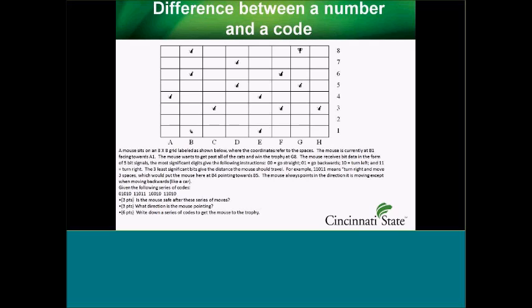It's a 5-bit string with the following instructions. The two most significant bits: 0, 0, the guy goes straight; 0, 1, he goes backwards; 1, 0 turns left; and 1, 1 turns right. The three least significant bits give the distance that he's going to travel. So 1, 1, 0, 1, 1 means turn right and move 3 spaces. The mouse turns like a car, so it's facing the way that it's going, even when it's backing up.